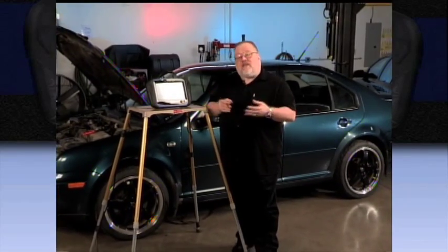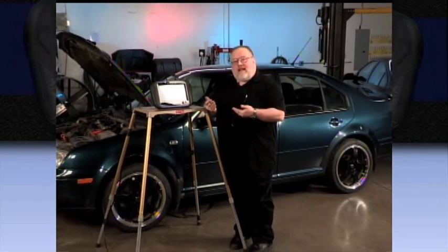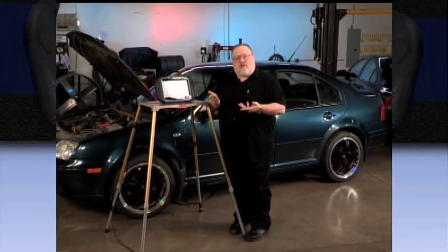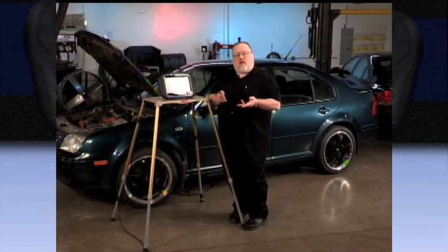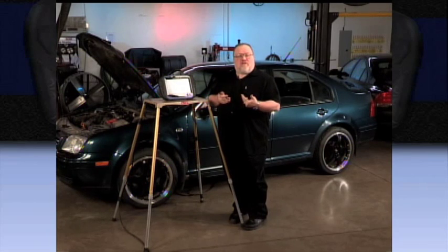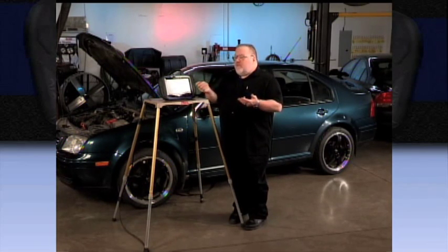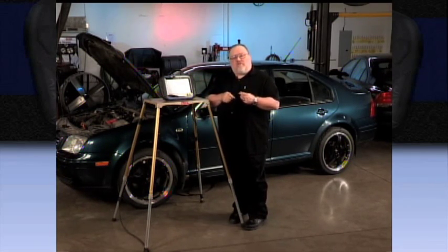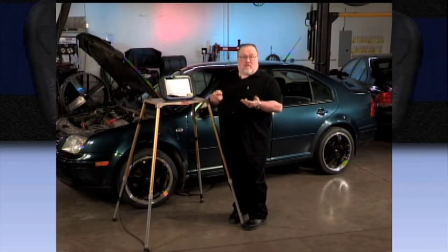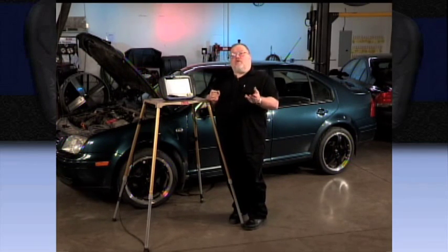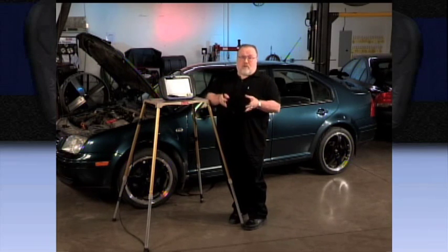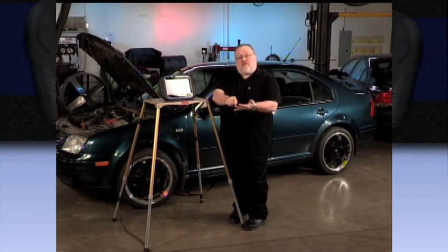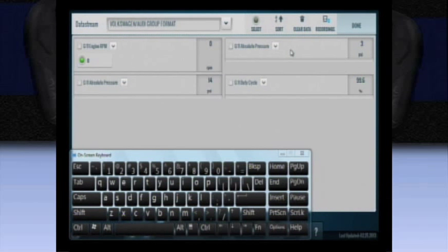So in this case, what I'd be looking for at wide open throttle, somewhere in the neighborhood of about 4,000 RPM under full load, is about 2,100 millibars of boost. And as you can see, if the computer is asking for 2,100 millibars of boost and I only have 1,200 millibars of boost, I've basically got no boost on this vehicle at all, meaning that I've got a problem either, once again, with the engine not being able to breathe properly or with turbo function.